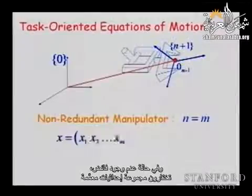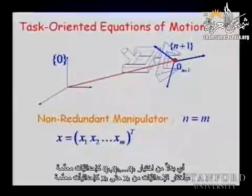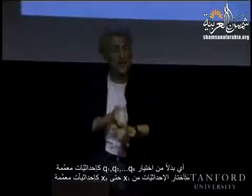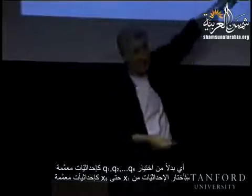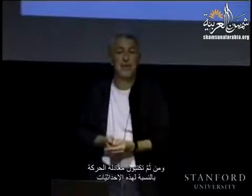And in the non-redundant case, you select a set of generalized coordinates, which are going to be your x, y, z, alpha, beta, gamma. If you have 6 degrees of freedom and an end effector with 6 degrees of freedom, basically what you're saying is, instead of selecting q1, q2 to q6 as generalized coordinates, I'm going to select x1 to x6 as generalized coordinates. And then you write your equation of motion with respect to those coordinates.